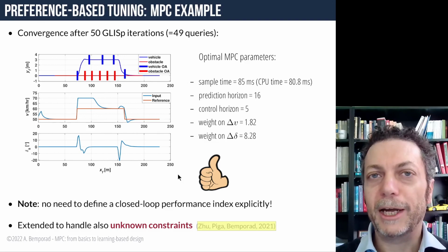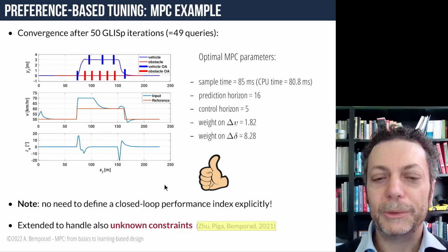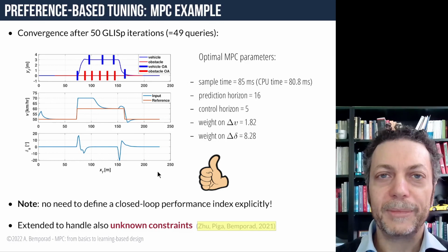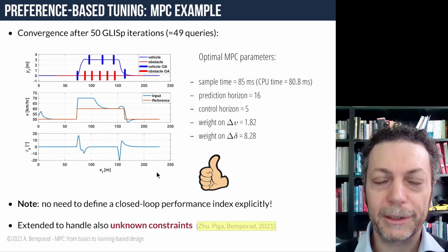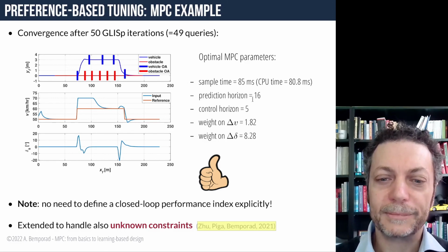So when you calibrate parameters, there are some combinations which are infeasible. For example, when the closed loop gets unstable, that means that selection of the parameters is not viable. It doesn't satisfy the constraint of keeping the closed-loop system stable, so you cannot even quantify a performance index in the case of auto-tuning.